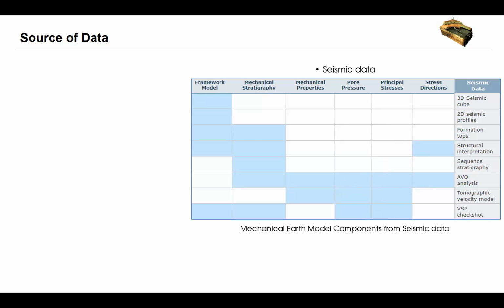Here is the point. The seismic data provide the structural and rock property information over the entire volume of interest. And also, the seismic data can provide a good comparison between paleo stress and present day stress state. How? For example, suppose that we have in situ measurements in one well. We have calculated our present day stress.